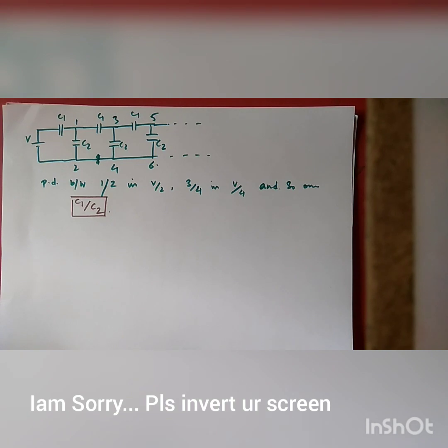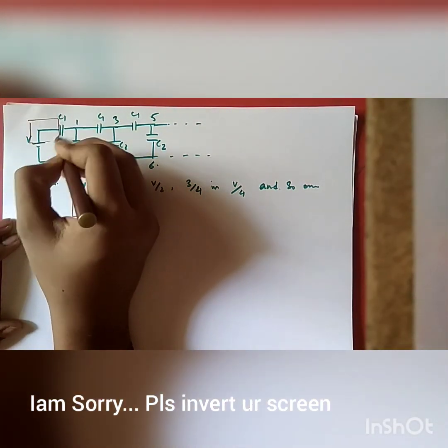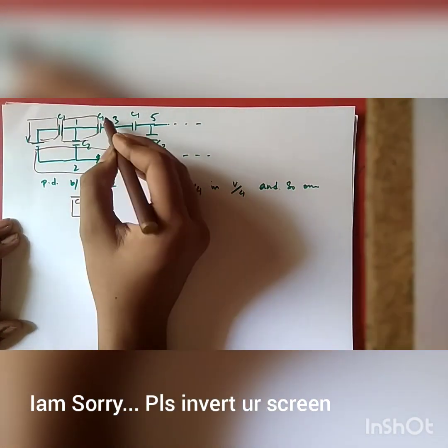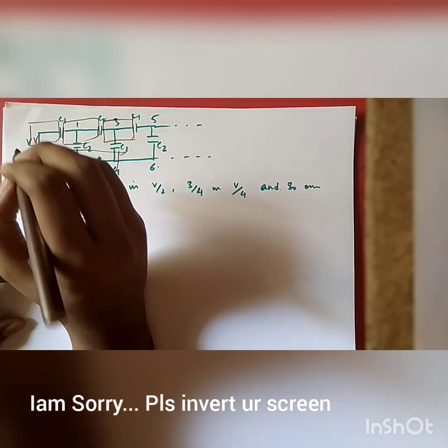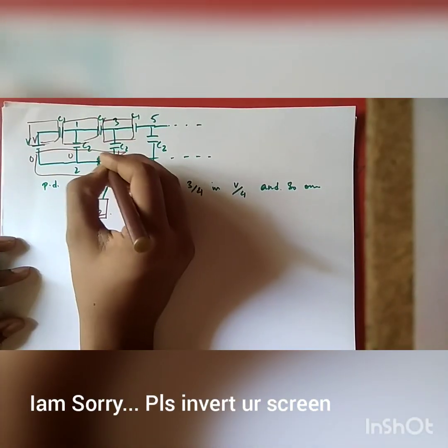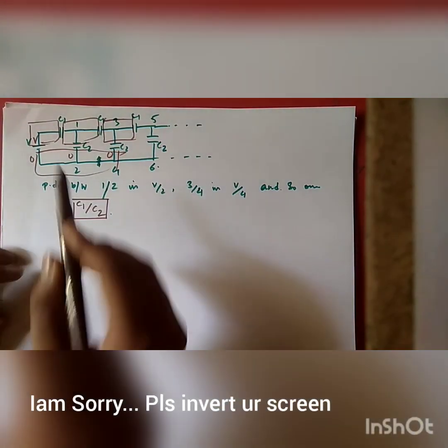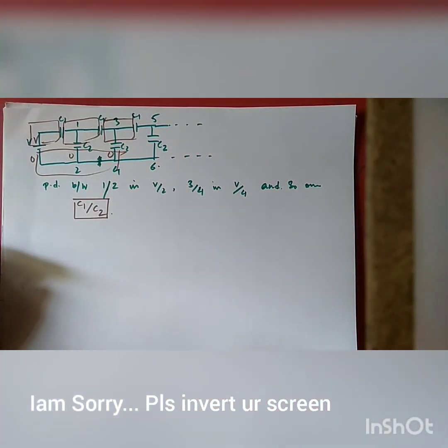Let us do the exact same thing which we did for the previous sum. Let us take isolated plate systems. So I've highlighted the isolated plate systems, and you know about taking the reference voltage potential, right? We will take it as V here and 0 here. So 0 here, 0 here. And in the previous case, we considered the potential difference here to be x and here to be y, because we don't know about it.